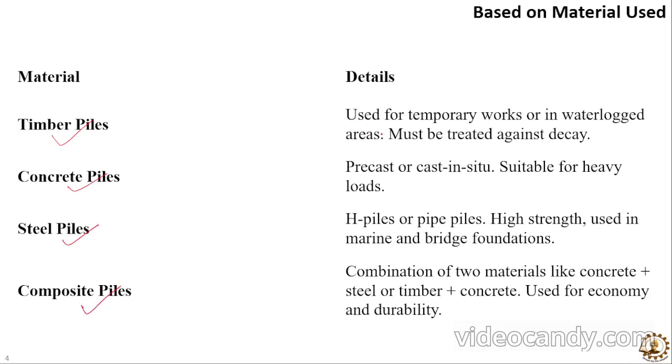Timber piles are used for temporary works in waterlogged areas and must be treated against decay. That means timber is an organic material, so with time it will decay. So we need to treat the timber so that it will act against the decaying of the wood, and the longevity of the timber pile can be enhanced.